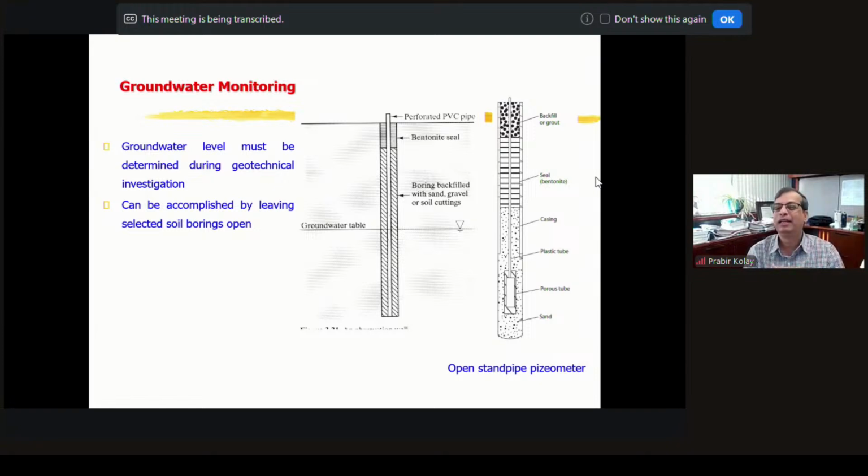If there is clay type of soil, water will not come into the borehole immediately. So we need to keep it for 24 hours and then measure the water. When the water level is steady, it means that all the surrounding water has already come into the borehole. Again, there are different perforated pipes, and sometimes we need to use steel pipe with grit, and sometimes you also use geotextiles.